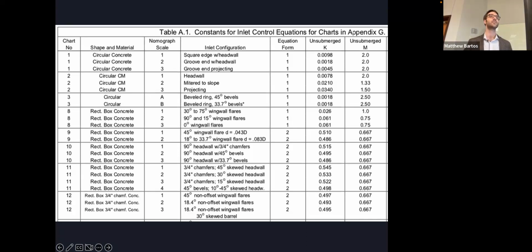If it was a rectangular culvert, what would D be? It would be the vertical dimension. D always refers to the vertical dimension. Typically, in the classical design for culverts, you would assume a width and then design for the vertical dimension. But you can also design for both at the same time, iteratively. But D essentially refers to the vertical dimension.